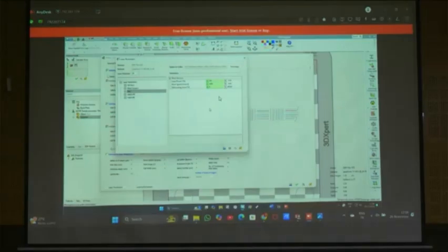The geometry we use is cube samples. While doing the optimization, everyone prints cubical samples, 5 by 5 by 5 or 10 by 10 by 5, with 5 mm height only or 2 mm height. They print it and test the relative density using Archimedes principle, and do the microstructure and everything. Using the Archimedes principle relative density, they find the porosity, the external porosity.